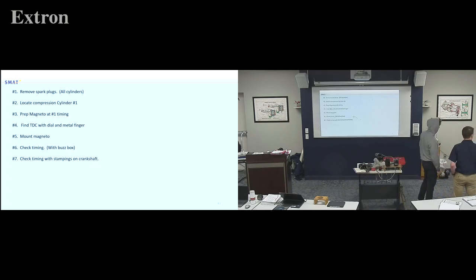What I want to know is when it's all the way at the top. But what I'm doing is stopping it before it gets to the top, so I'm stopping it here, right? And if I stop it there, and then coming around this way I stop it at the same point, top dead center is basically halfway between those two stops.